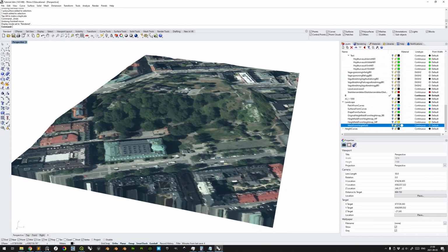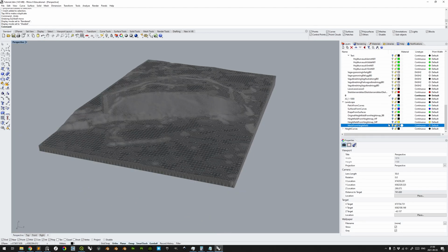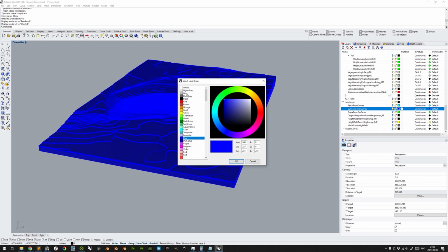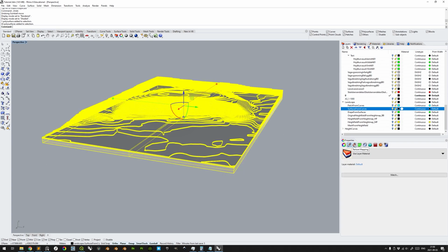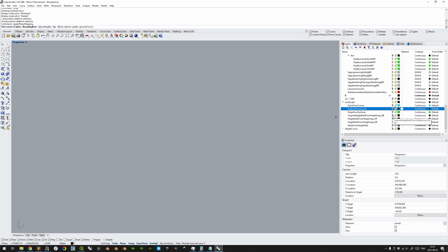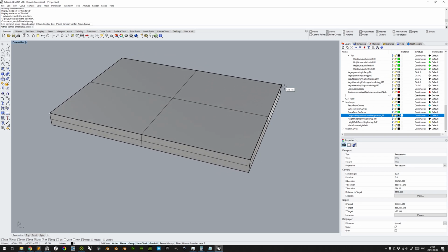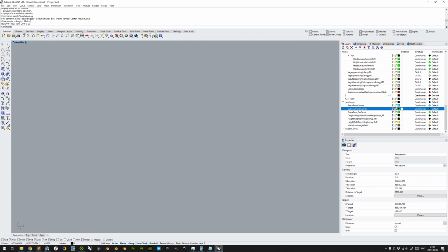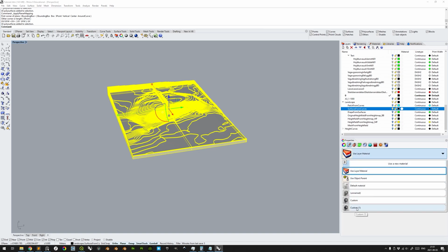All right, you decide yourself which one you prefer, and a side bonus as well is that if you go to, as an example only, the surfaces from curves, if you change this back to black, and then if you select all of these, go to texture mapping, apply planar mapping, and do as you did previously, temporarily disable the showing of the actual geometry, and then show this bounding box of the imported height field, and then confirm it as a UV mapping, and then show it again, select everything again, and then assign the material. And now I just guessed that it was this custom one that we made previously.